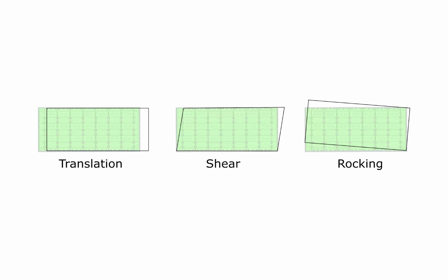The second mechanism is a shear, and it's due to the fact that we have some shear panels, shear facades on both sides of the wall, which made the cassettes, which are subjected to shear as well. So we have a deformed shape like this, and you will see later there's actually a very nice formula, which is a pretty well standard formula for calculating the shear deformation of rectangular walls.